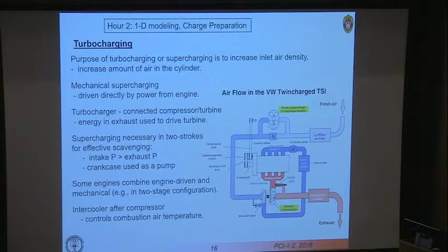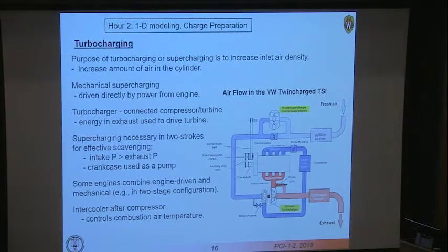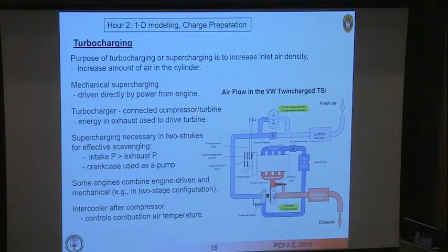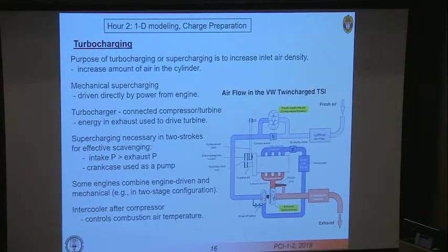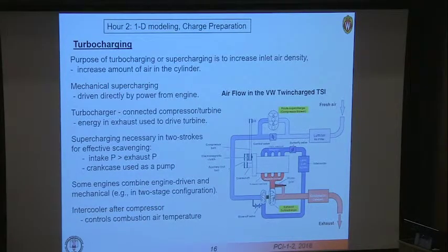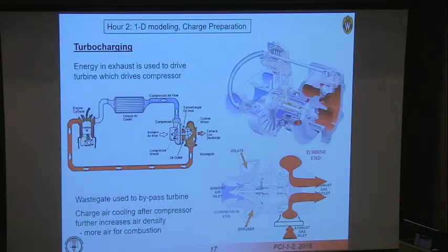Notice there's also the introduction of an intercooler here, and the idea there is you've compressed this gas and increased its temperature, so you cool it with an intercooler that's water-cooled, for example. You can now increase the density of that gas and thereby get more mass into the combustion chamber. So managing the airflow is a key component to generating high-performance engines.